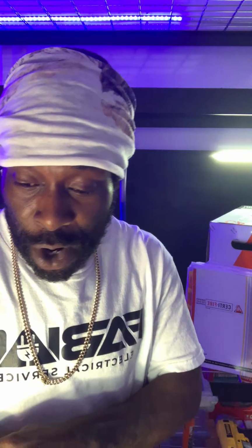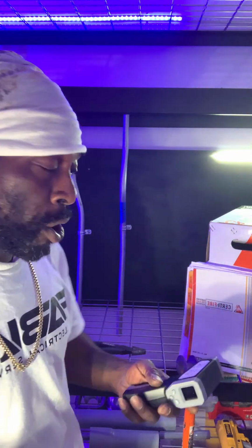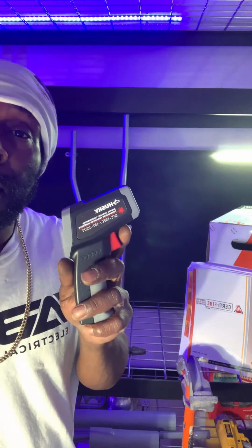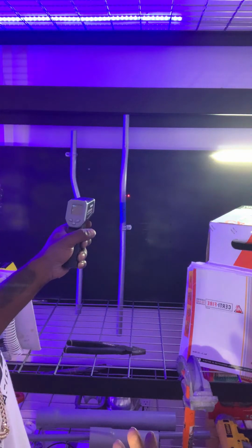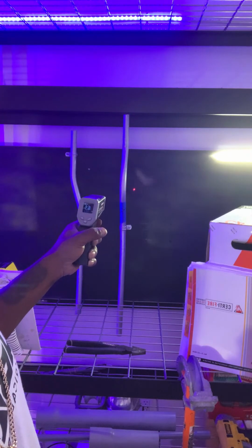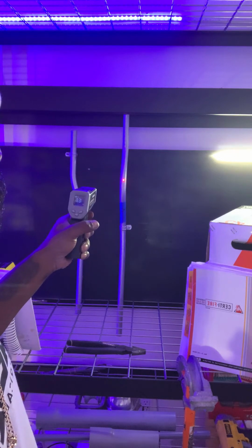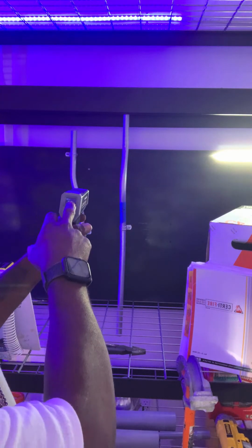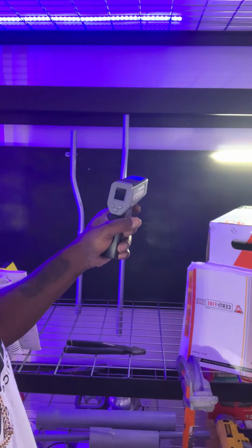So again, with 2-inch conduit, very important when you're using the 2-inch conduit, and don't forget also to check your temperature. When you check your temperature inside the conduit, you simply turn it on and point the laser inside of here, and it's going to show you what is going on. It's going to give you the temperature that the conduit is heating up. Okay, so basically what I'm doing is scanning right here for temperature. I do the same thing over here.